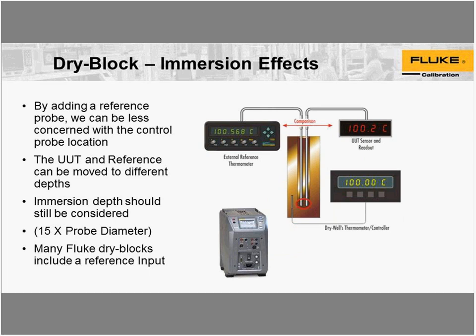All right. Now we're going to touch on immersion effects. Again, immersion usually has to do with the sensor itself. Depending upon the makeup of the sensor, sensor lengths and diameters vary in the UUTs. And then also the outer sheathing. These things kind of play into immersion depth for a probe.